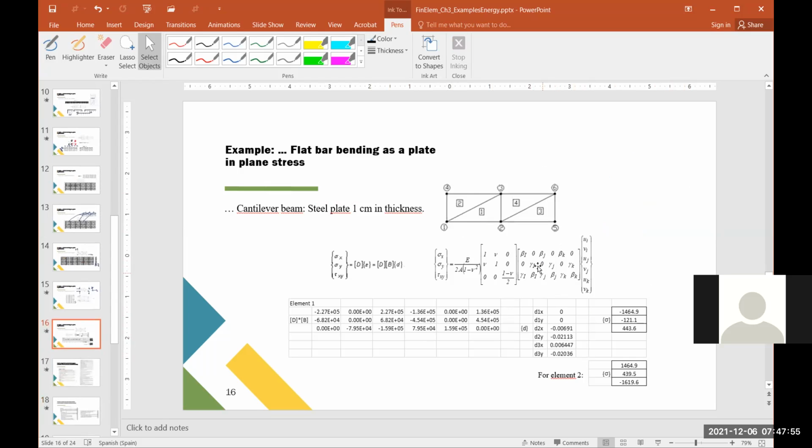And then we go element by element. This is the definition of the stresses. So this is what you have to do in order to get the stresses. Again, see, this beta has units of length. This displacement has units of length. A is F over L squared, so A is length squared. We cancel this, and we have the units of stress. So every time we do these calculations, we should check units, okay?